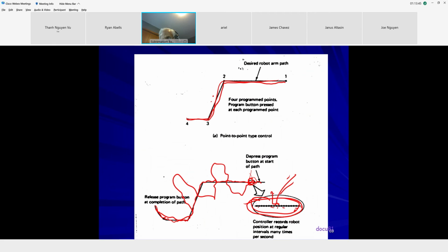Okay. Now, what would be an example? I told you about spray painting. So if you have a panel that you want to spray paint, like the hood of a car, which is before assembly is painted, let's assume, and it is coming on a conveyor dangling, what you would do is to have an experienced painter teach the robot exactly the way he would paint if it is manual operation that will satisfy all quality control.